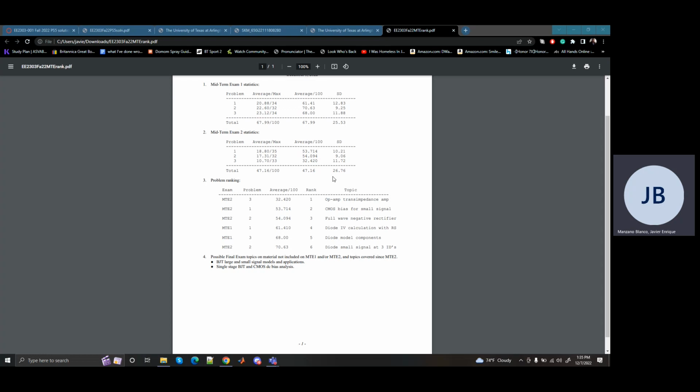let's demystify this real quick and talk in simple terms about why these capacitors are there. If I'm going to amplify a signal, like a voice on a microphone, that signal can go positive and negative. It's a sine wave. So that input signal is going to be like this.